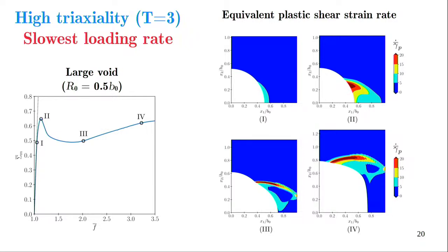Now you can see this has almost become straight, which initially was a circular shape, and this part is now expanding just like a uniaxial specimen. So when the fracture happens, it will probably happen here somewhere.